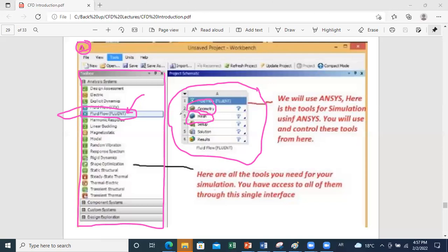So you'll be familiar with these terms. In general, this step is the most difficult because sometimes you need to reiterate. After doing the solution, if you find divergence, or if you find your physical results not very logical or not comparable with real results, you should go back to your mesh, try to enhance its quality, and then go back to your solution.